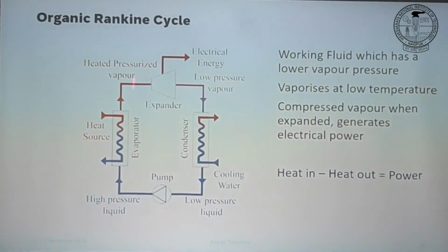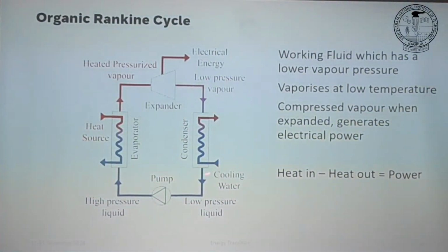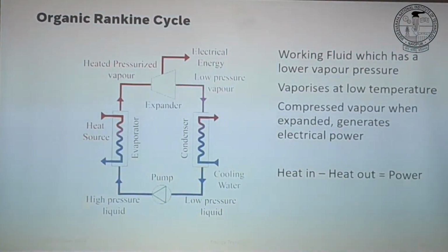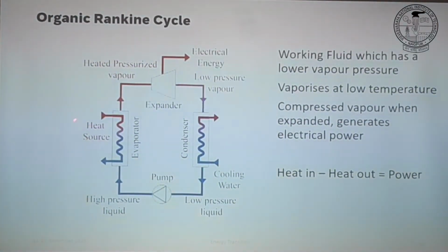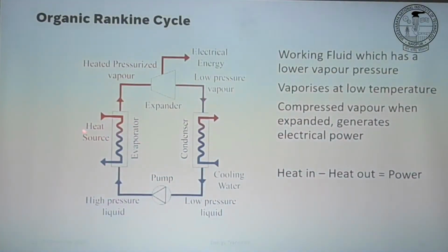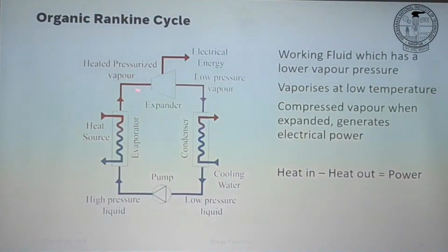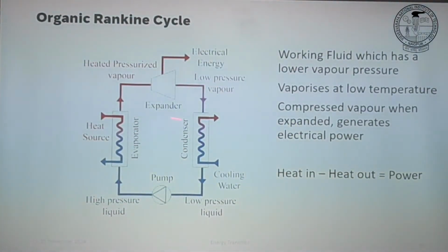It's very common nowadays, especially in the cement industry. So once again, you have flue gas at 100 degrees centigrade. You know what to do. People normally exit it in the atmosphere. But what you can do, once again, is use another organic fluid, right? And use this flue gas at 100 degrees and exiting at 50 degrees to vaporize at high pressure this organic fluid. High pressure organic fluid will be turning the turbine, it will be expanded while generating electricity, goes to low